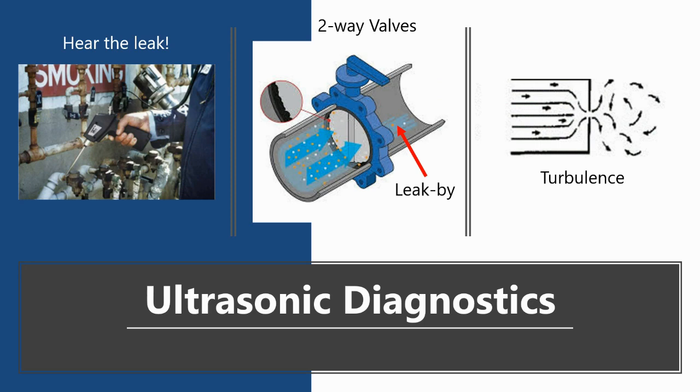Two-way valves with straight through flow are pretty easy to figure out what they're supposed to be doing. If the valve is completely shut, the valve should essentially be silent. But if there's leakage, then turbulence will be formed as the steam or water squeezes past the valve seat. An ultrasonic listening tool does a great job of enunciating that noise generated by the turbulence.